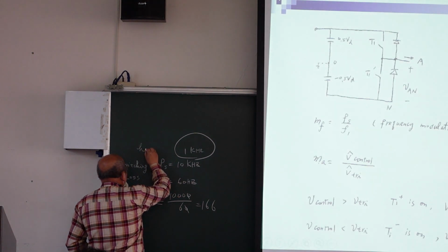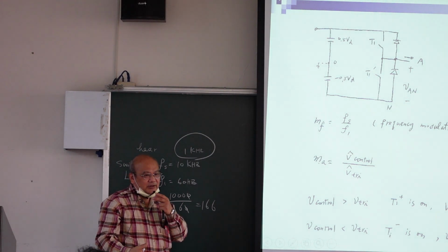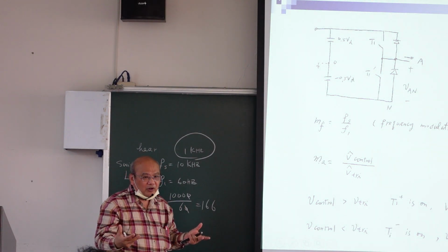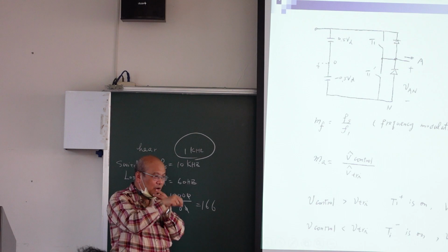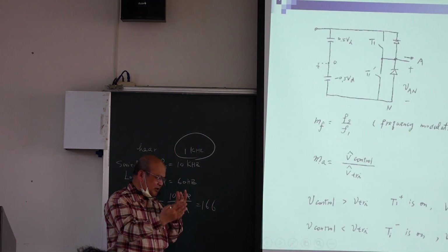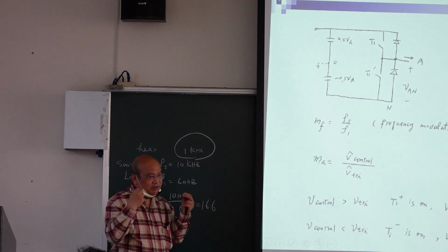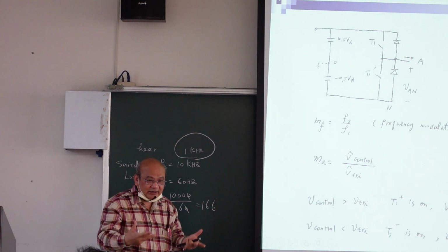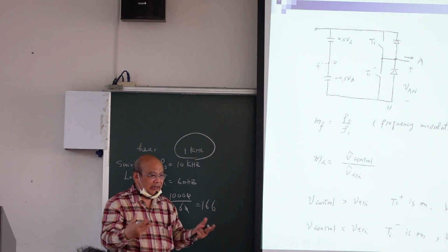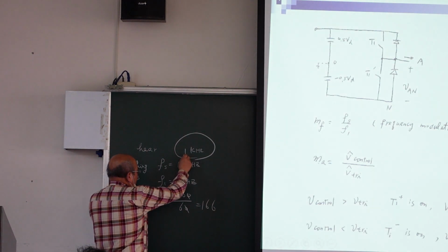You can hear 1 kHz clearly. Then you feel uncomfortable. And if you have a dog near the inverter and the driver, the dog will go crazy because his ear is more sensitive than a human's, so he cannot endure. So for this reason, we cannot set 1 kHz.